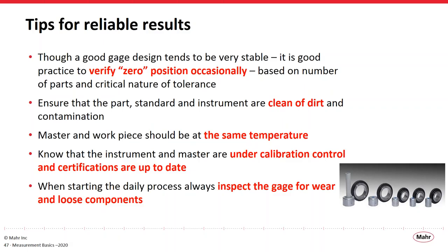It's becoming very critical to document the measuring process. That includes documenting the gauge, documenting the masters, and making sure that the right gauge was used to make the measurement on that part. All those things are starting to be controlled and documented today. And again, every day you should make it a regular routine to inspect the gauge for wear and loose components, to ensure that we're doing our best to keep the enemy out of our gauging process.